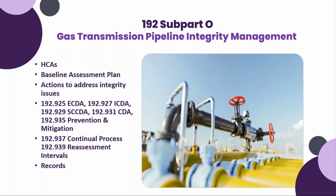And it detects only the coating anomalies, and then it has to be analyzed to determine if there's any corrosion going on. So it doesn't directly look for corrosion, it looks for coating anomalies. So keep that in mind. Of course, ICDA would be water holdup and things of this nature, and SCC would be similar to the ECDA, but more on the environmental side, to determine particularly where the shielding is occurring on the coating systems.